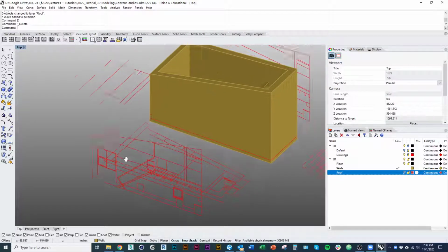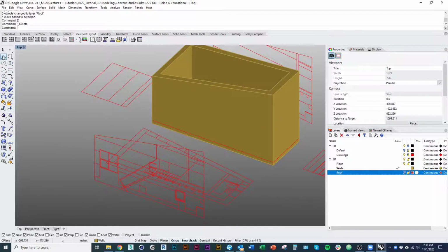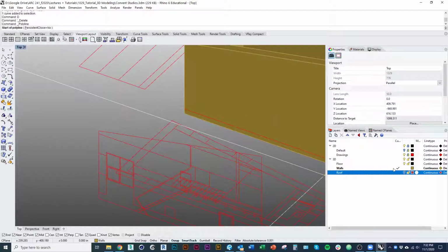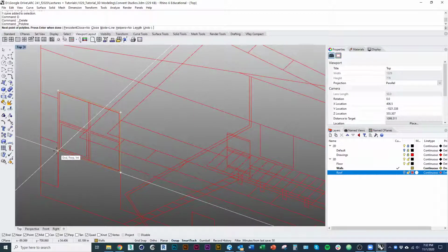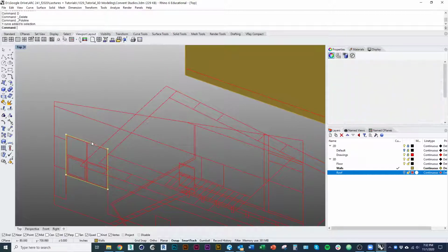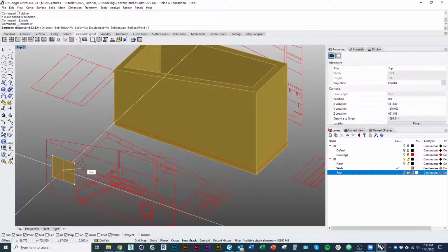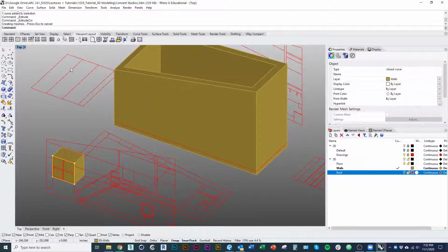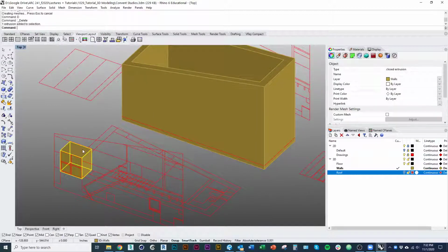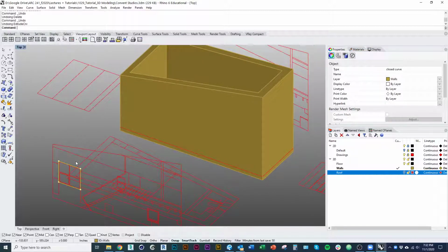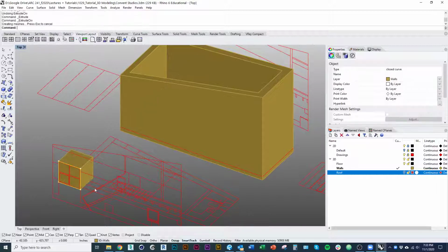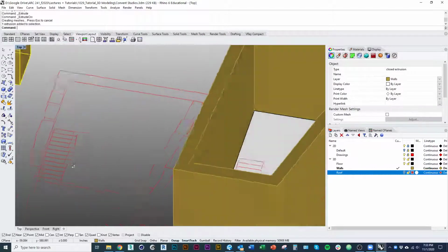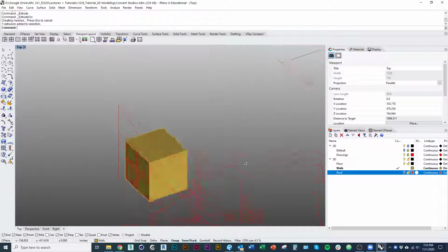So I can do kind of the same thing. I can make polylines. I'm still working on my wall layer because I'm still developing what my wall is going to be. I'm still making the cutouts and everything like that. So I can extrude this guy, and I do want to make sure that the option Solid is set to yes. So one more time, that option Solid set to yes, and that means I get a closed poly surface when I extrude that guy.